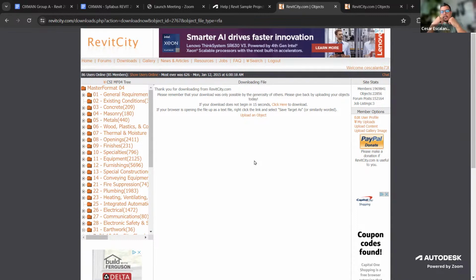It was just a standalone floating object that wasn't created through Revit. And a lot of these imports sometimes bring CAD definitions that Revit cannot interpret. That's the source of corruptions, or the start of the sort of corruption in some projects. So if you see imports from CAD, no, don't use it. Use something that is truly built in Revit geometry, and it's easy to diagnose. You open a family, you select the object, and it will be called DWG import. And I'm like, no, not really.